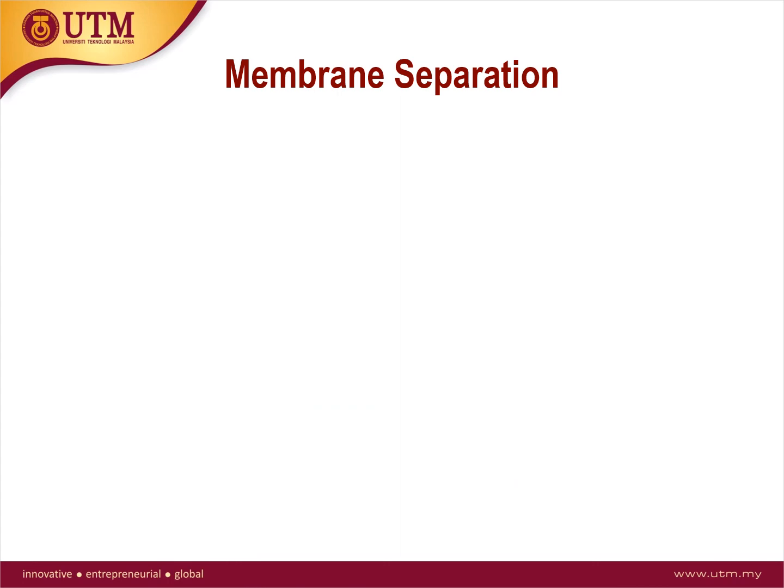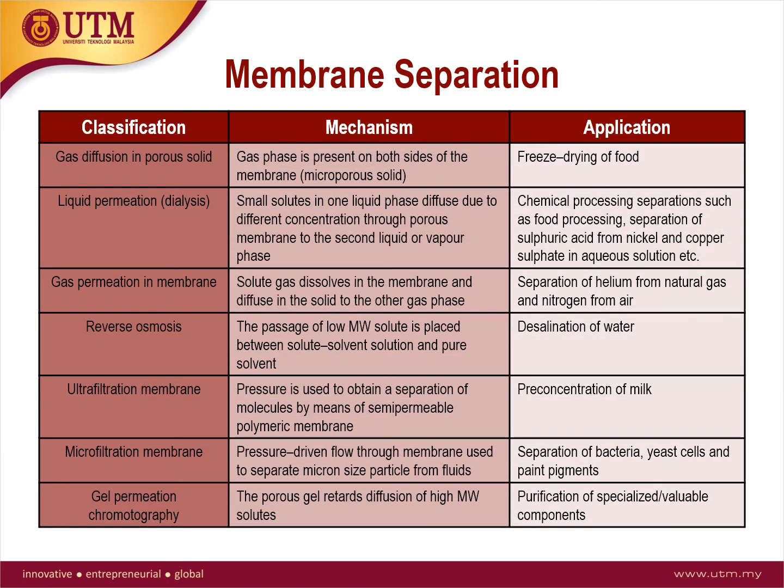Membrane separation technology can be classified into four major operations: pressure-driven operation, concentration-driven operation, operations in an electric potential gradient, and operations in a temperature gradient. The pressure-driven operations are microfiltration membrane, ultrafiltration membrane, nanofiltration membrane, and the reverse osmosis membrane. Based on this classification, they use pressure as a driving force.